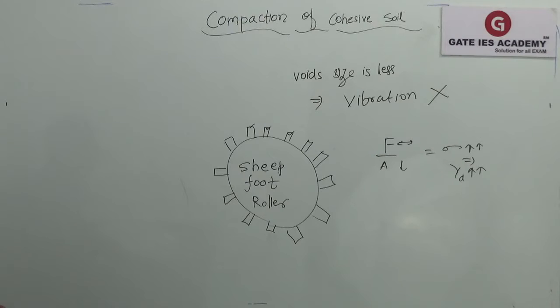In compacting clays, the position of the particles must be changed by forcing the contact points along the adjacent surface to positions more parallel, thereby reducing the voids.